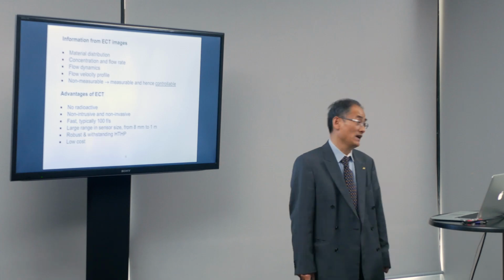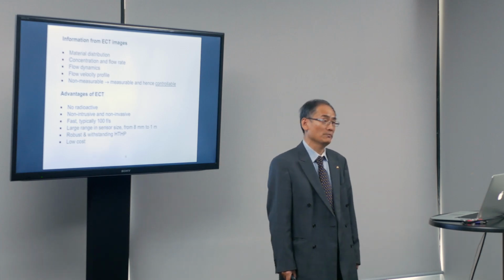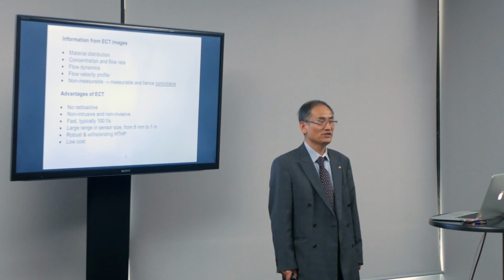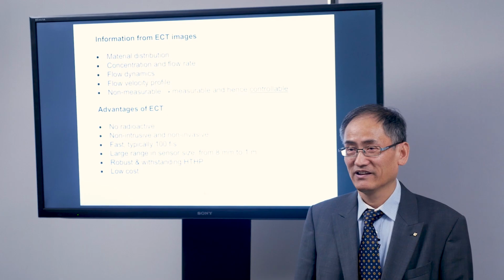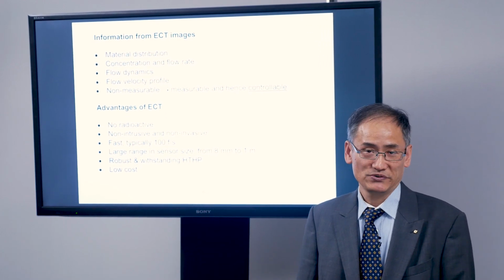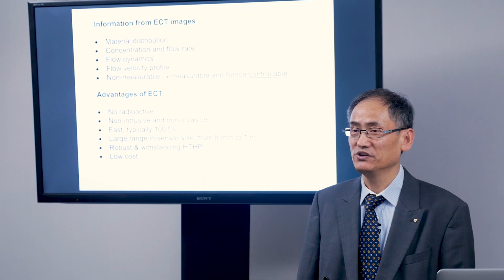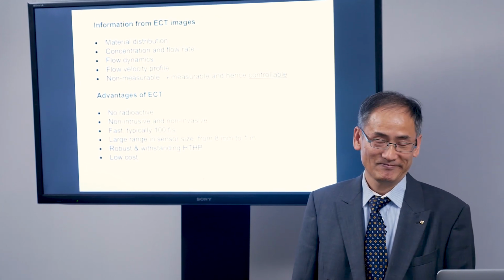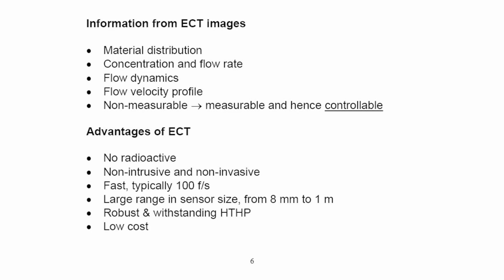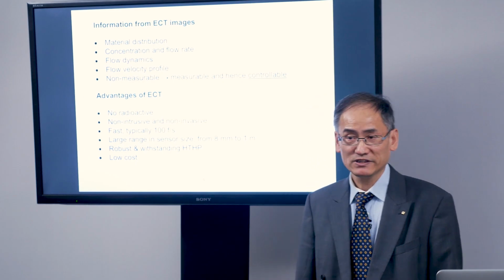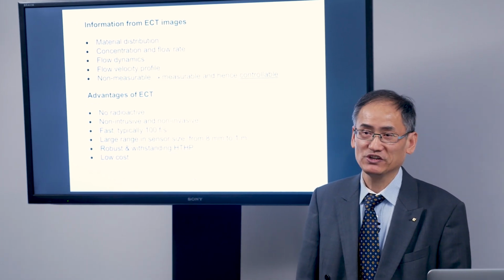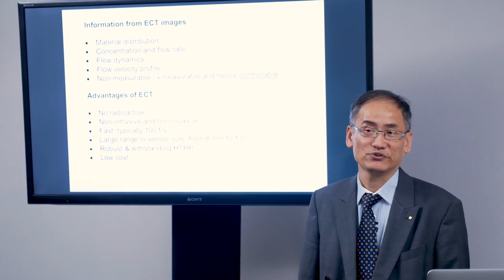There are many different types of tomography systems. ECT is one of them. I can summarize the advantages of ECT in the following part. Non-radiation, non-intrusive, non-invasive, which is very desirable by industry. Fast, the typical speed is 100 frames per second.